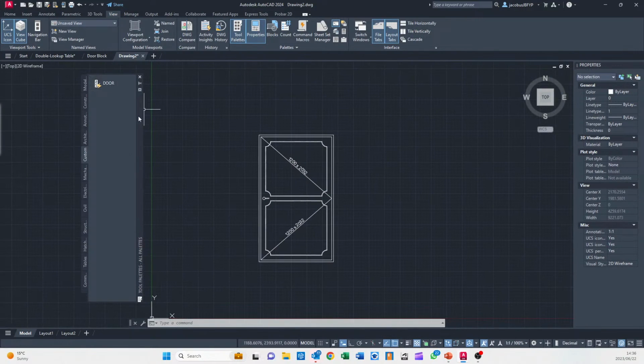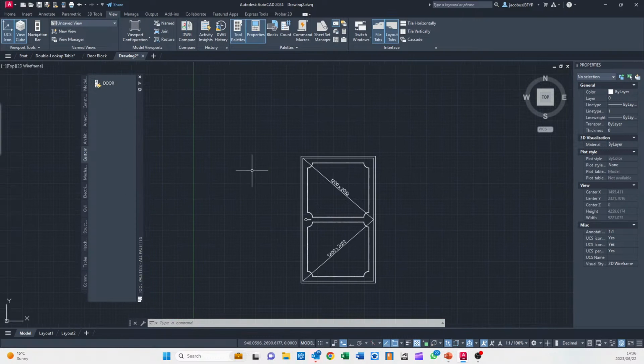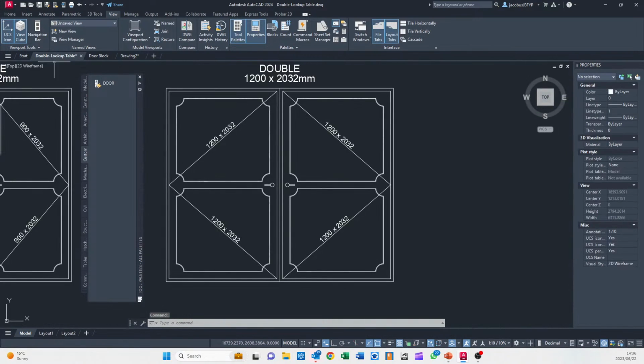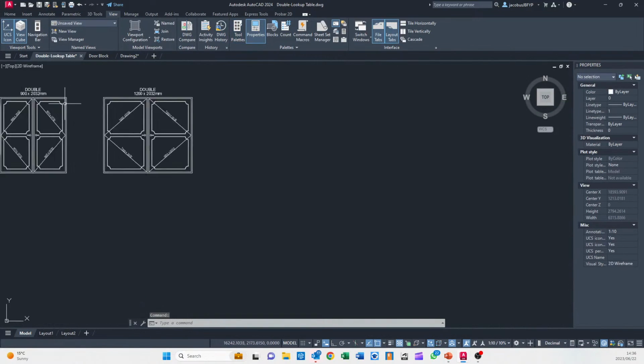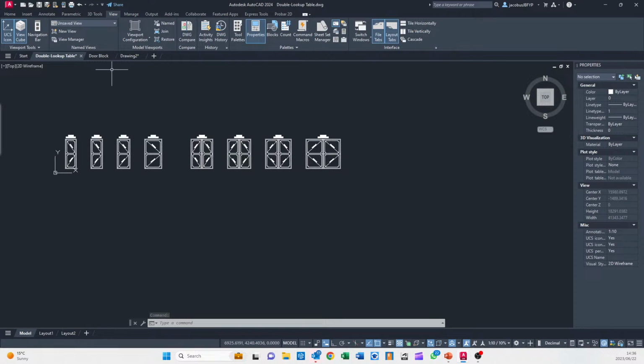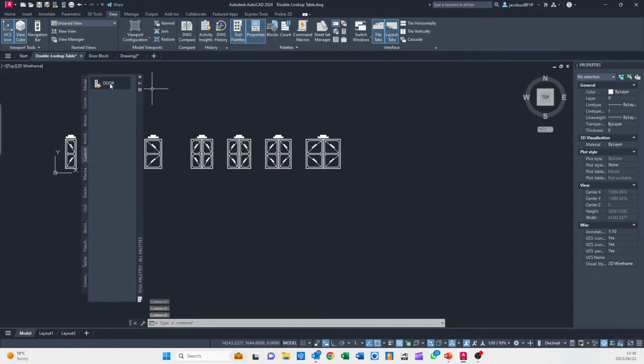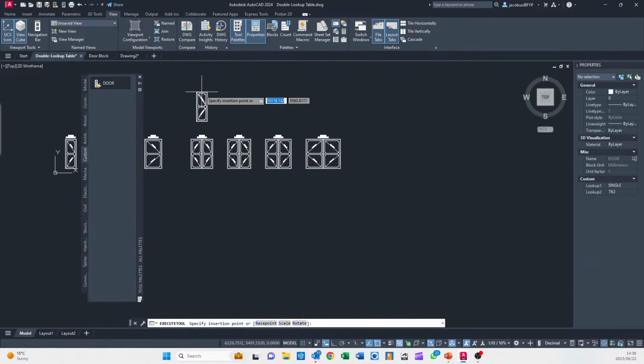And that's it. I really do think that creating a custom tool palette and adding these dynamic blocks to that custom tool palette is the best way to go about it, rather than creating additional folders. It's easily accessible now in all of your AutoCAD 2024 drawings. You can even go to older drawings. This drawing, of course, predates the creation of the dynamic block. Go to tool palettes, and there it is.